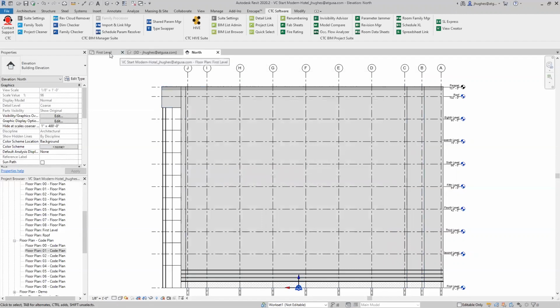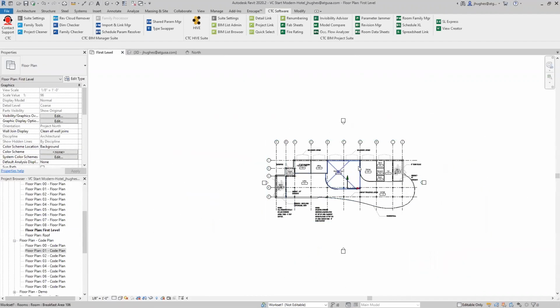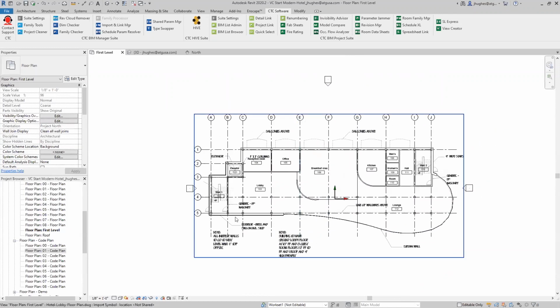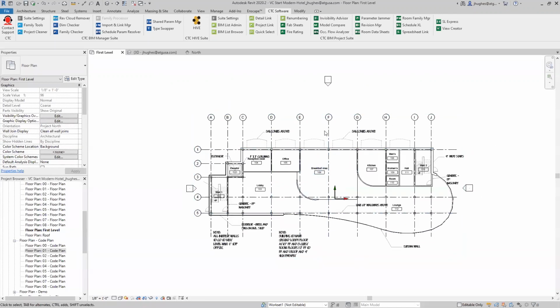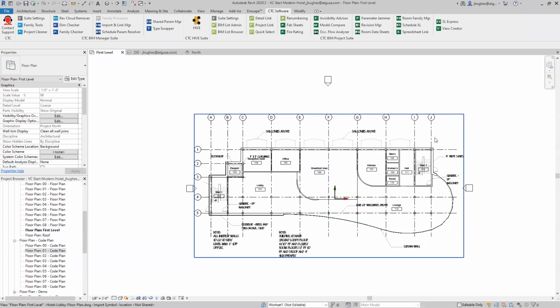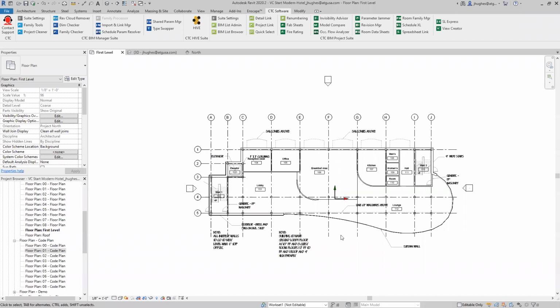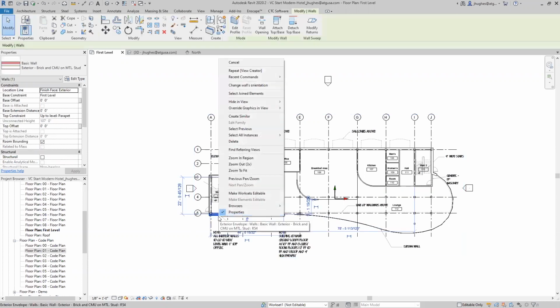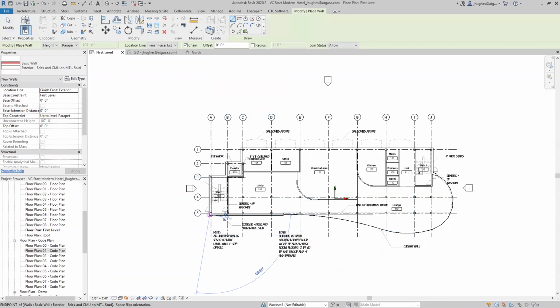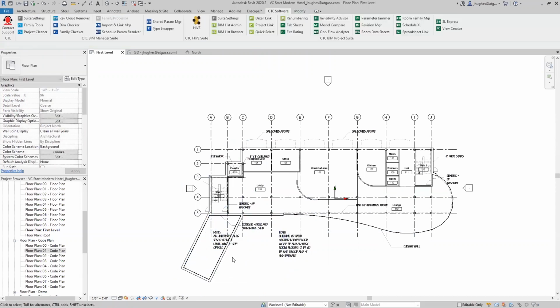So I'm going to go to a first floor view here. And here is the general size of our project. We're going to create an area that's on the left side, and we'll basically split it somewhere around column line F. And so then we'll have a building on the right, and we'll just call that area A and B. And actually, to demonstrate something else, I'm going to draw something out on an angle down here. We'll just use one of these existing walls, create similar. We're going to make sure that we introduce an angle to this, and then I'll stay orthogonal to that angle that I introduce. And we'll show how a scope box can actually help with your project north in this scenario.